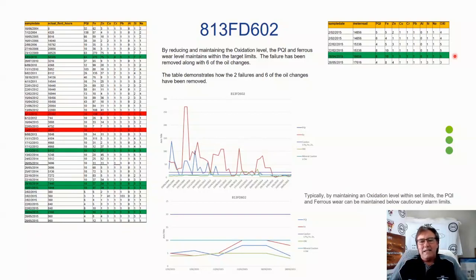We needed to maintain the levels below, right, from a 3 ppm for dirt signature and an oxidization level, to be able to then eliminate the gearbox failures. These gearboxes are designed to go for 10 plus years. So we were finding over the course of 4 years, 5 years in this case study, we had changed these guys out twice. Right?